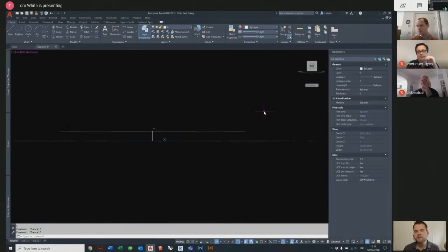Just on moving around your views, do you tend to click the top left? Yeah, it's top left, or using the box in the top right hand corner. I tend to go to that quite a lot and just flip it around. Yeah. Cool. But I'm also holding Control and the middle mouse button and dragging my drawing around as well. Yeah, gotcha. I've got 3D habits that way as well.